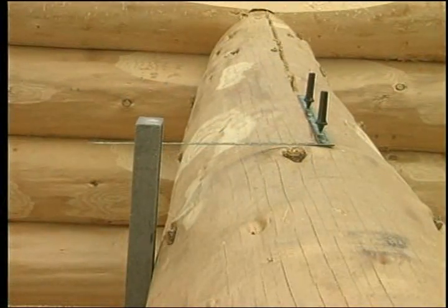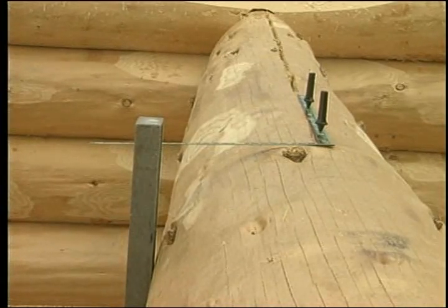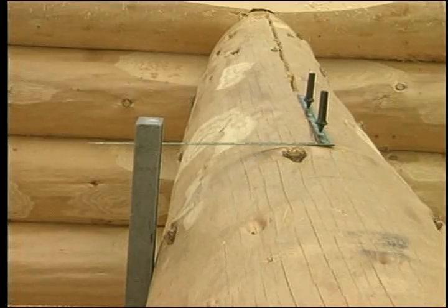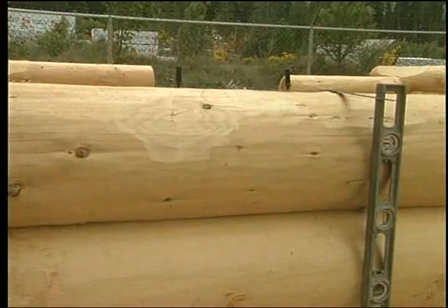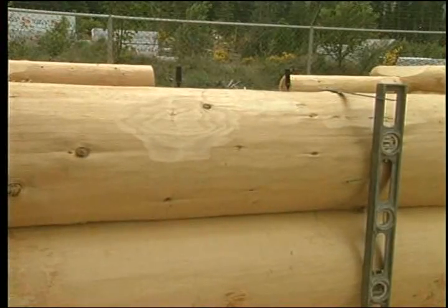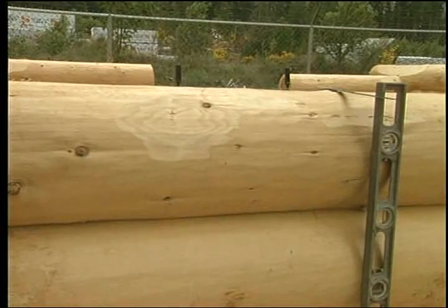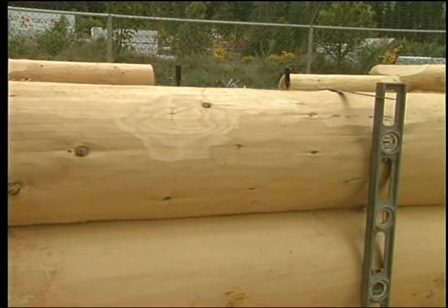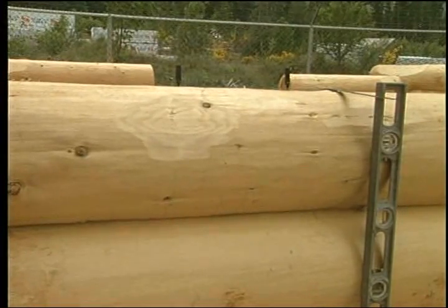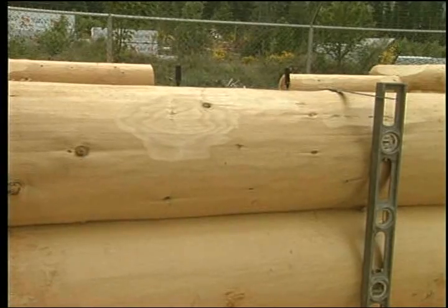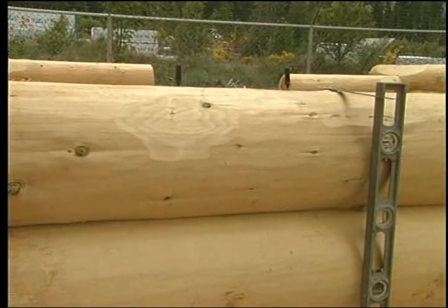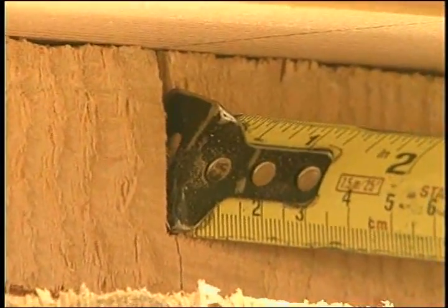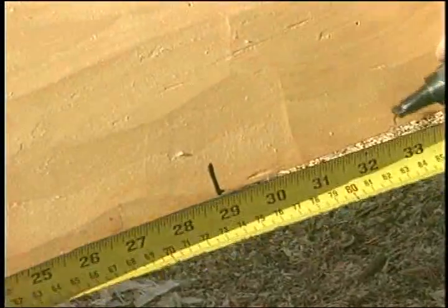If you do not have this location, measure it onto the center line of the header log and transfer it down to each side with a square on the center line and a level on the side. Or measure from the center line layout you cut onto the top of the stump.